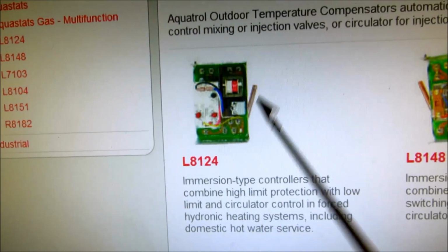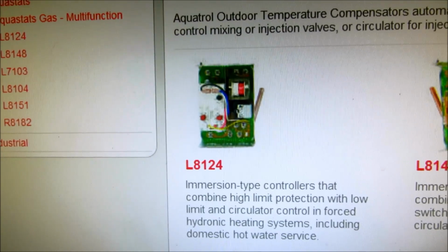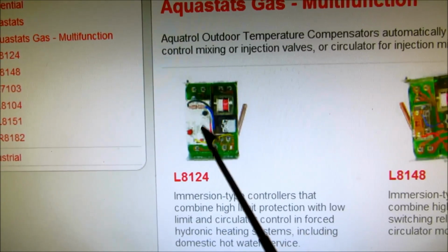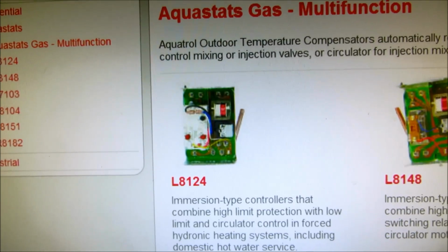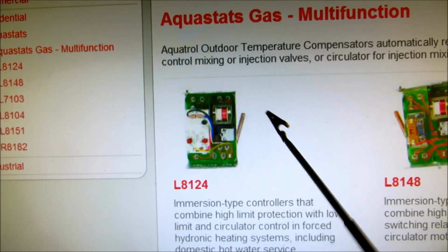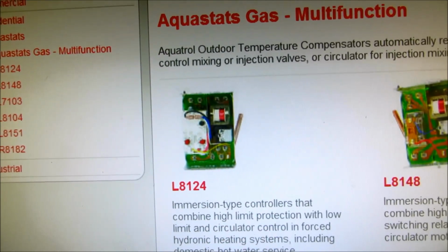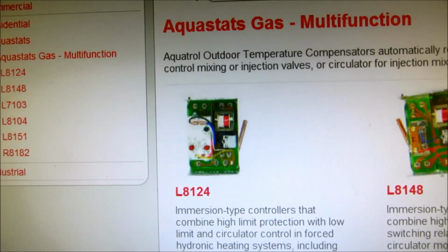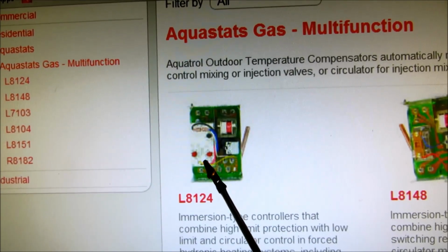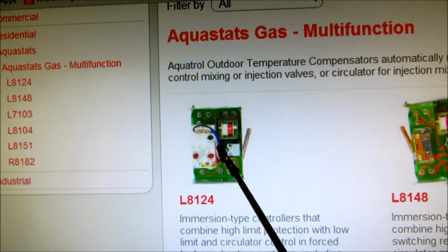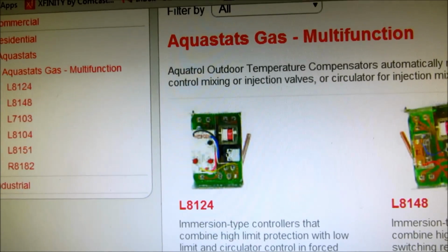So you could take an oil burner control like this and put a step-down transformer and feed the burner with that. Would be no problem. Now, the only reason why you'd want a low limit on a burner control, this is the main operating control for a boiler, the low limit would shut the circulator off, so you could use priority on a domestic water zone for either stored water or a tankless heater. That was the only reason why you'd need the low limit. So in other words, when this thing was below whatever that low limit set off, the circulator would shut off.